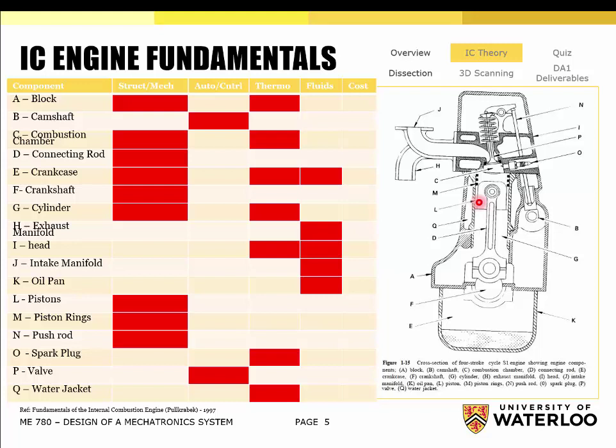So if you think that the piston itself is actually one wall of the combustion chamber, it's getting exposed to a lot of heat, just like the other walls are. Okay, but it's made out of aluminum, so that's a difficult thing to manage, and it has nowhere really to dissipate the heat other than through the piston rings. The cylinder head has all those fins that are attached to it that it can dissipate the heat to the atmosphere or the ambient condition. But the piston really has nowhere to go, so the rings are the things that really allow it to extract heat.